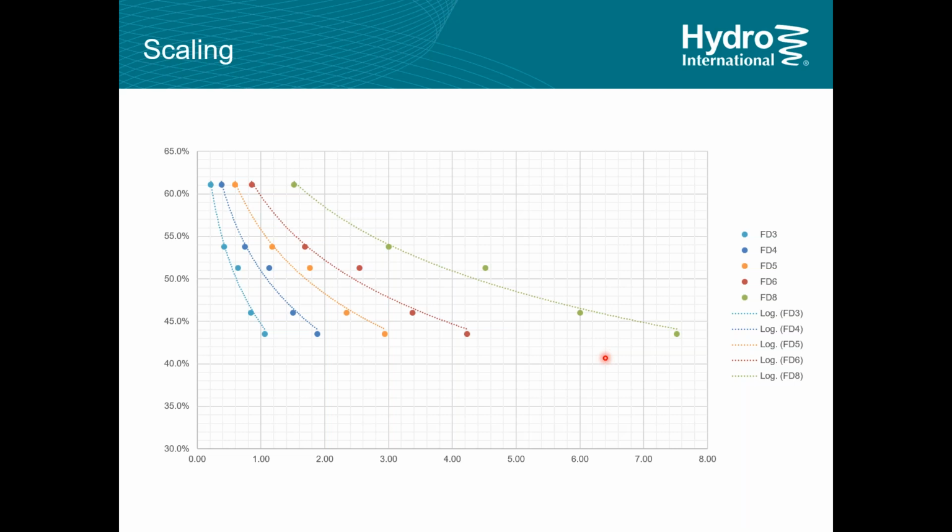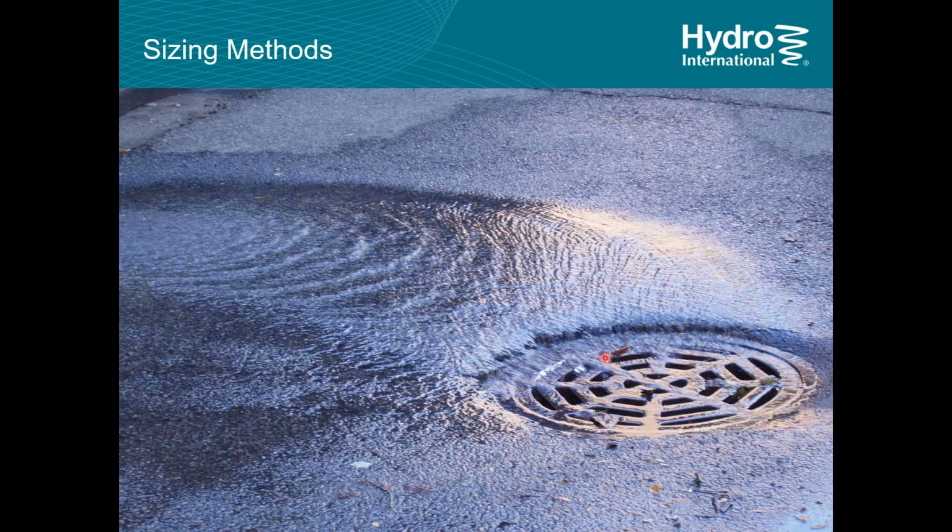It's the same way we scale ponds. It's the same way we scale any surface area type system, and that's most commonly used now. So most tools will use that. There are some regulators out there that have allowed quasi sort of 3-dimensional scaling, where depth comes into it, and instead of using a factor of 2 for your scaling, you might be using 2.25 or 2.5, because it's not strictly a linear scaling. They allow a non-linear scaling.